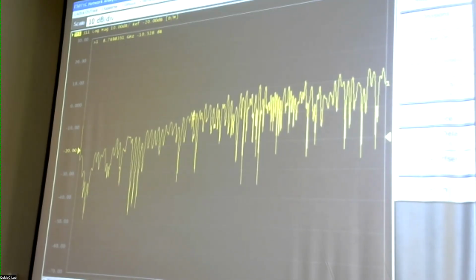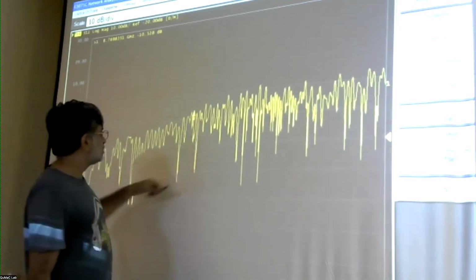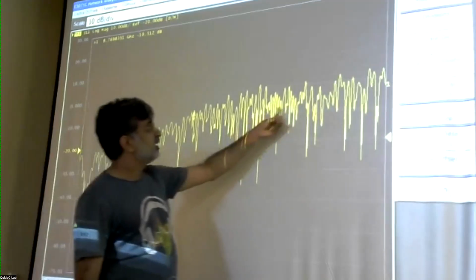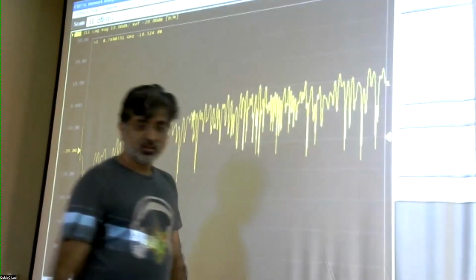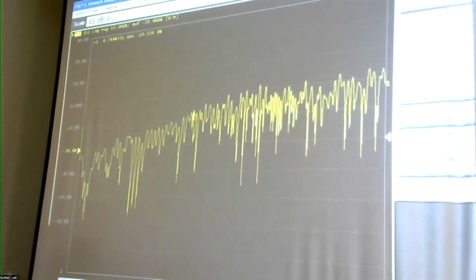So here you are seeing a fairly low level out here at low frequencies around minus 30. This means 10 to the minus 3, right, in power. But it gets progressively worse. And of course, there are all these ripples here. And in fact, I'm surprised that it's almost at 1 at 20 gigahertz, which is kind of strange because, sorry, it almost is at 0 dB.